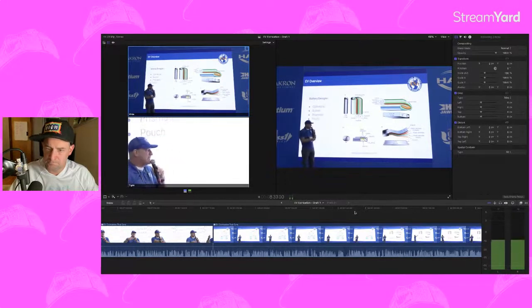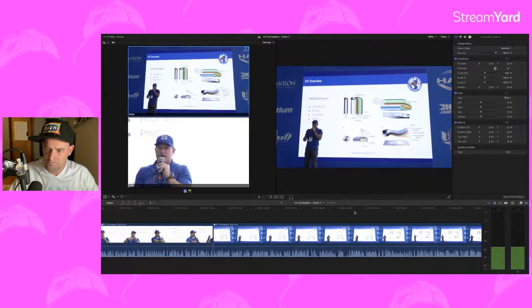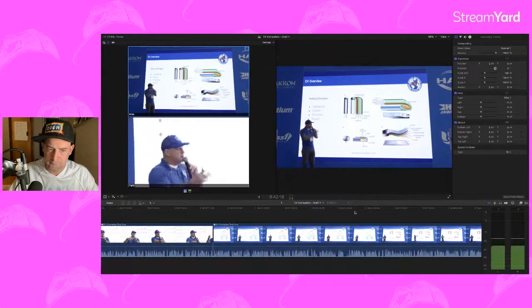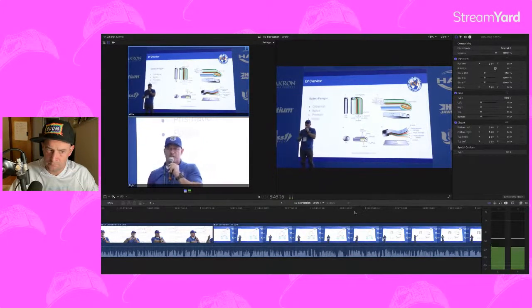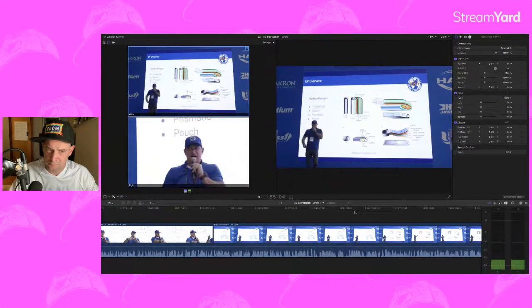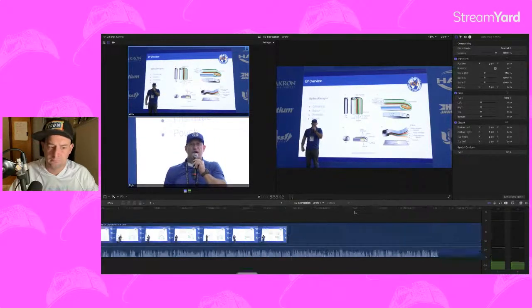The last one is button cells. Everybody's probably familiar with button cells because they think of watches and small appliances. But what I want everybody to understand about this slide is you may interact with every single one of these on one vehicle, okay? So what you need to understand is you may have cylindrical cells in your traction battery pack or the battery pack that's built into the floor pan of the vehicle.